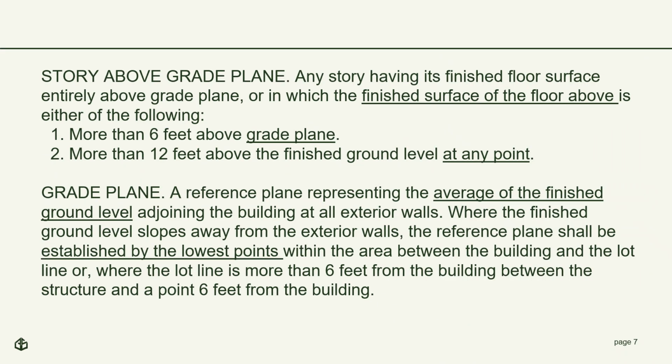Now that we've determined that the IRC is limited to 3 stories above grade plane, we must understand what's considered to be a story above grade plane. Defined terms are italicized in the code, and their definitions can be found in Chapter 2. The IRC defines story above grade plane as any story having its finished floor surface entirely above grade plane, or in which the finished surface of the floor above is either of the following: 6 feet above grade plane, or more than 12 feet above the finished ground level at any point.